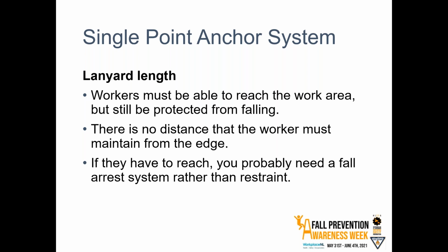You don't want to use an adjustable system, because again, it's been my experience that if you use a system that's adjustable, then the guys are going to adjust it. Guys or girls, I do mean, when I say guys, I mean that just in the royal we kind of scenario, to include both girls and guys. But again, we want to make sure that this length is fixed and that workers don't have the ability to adjust it. Because again, if they do, they might be tempted to do it, and then we're in a situation where they actually need fall arrest instead of fall restraint.